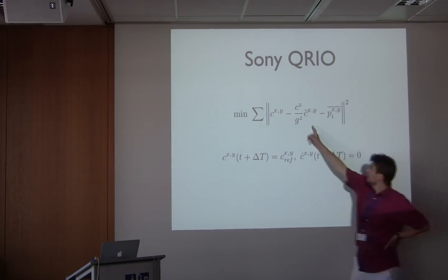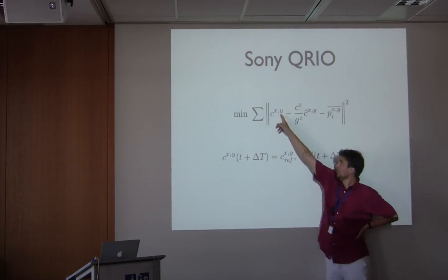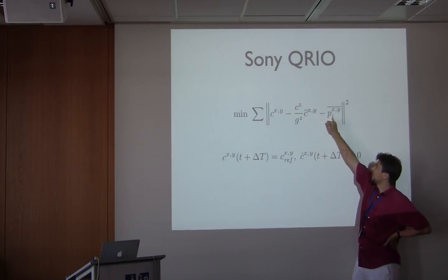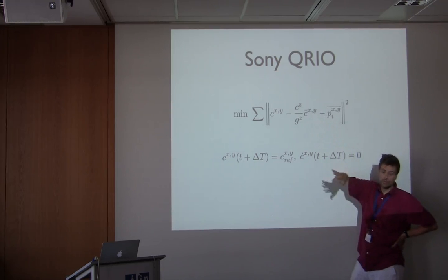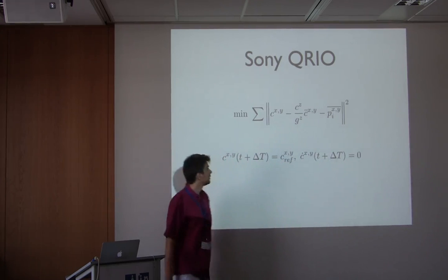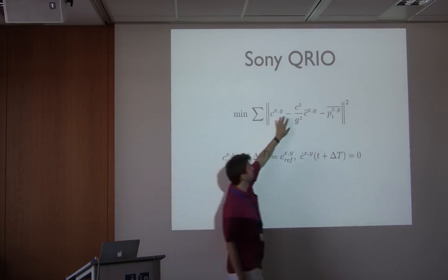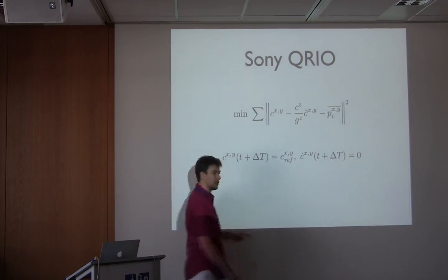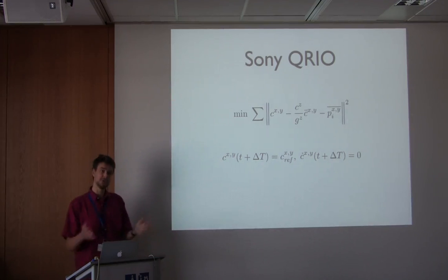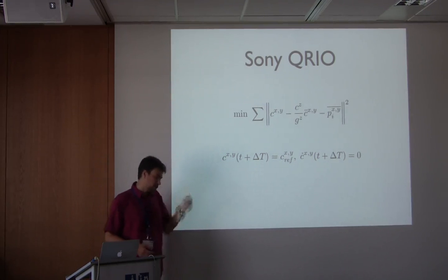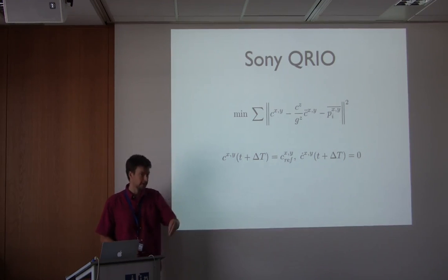What they did was use this single mass model that we've been working with, and instead of imposing that it follows a predefined motion and just leaving 1 or 2 degrees of freedom free, they said, well, let's try to minimize this squared sum, so we try to follow this as much as possible while imposing this constraint. So here is a constraint on both position and speed, so that imposes capturability. But maybe that imposes not only capturability but also stopping there.